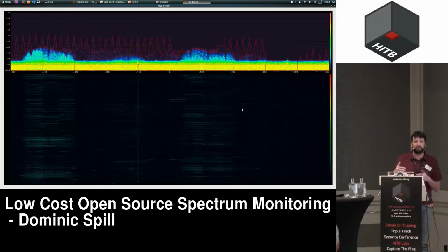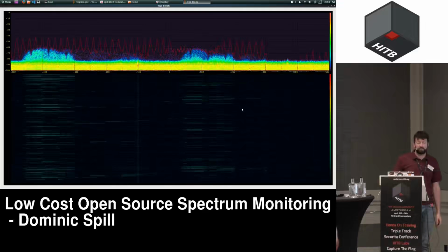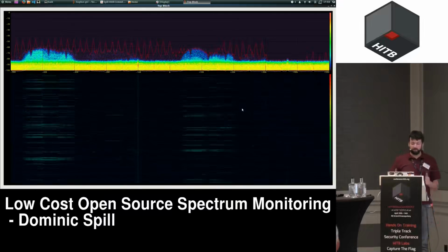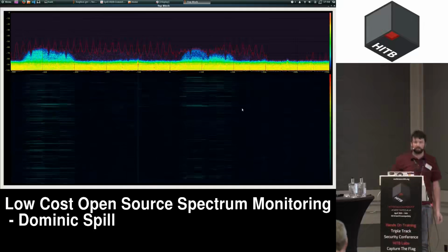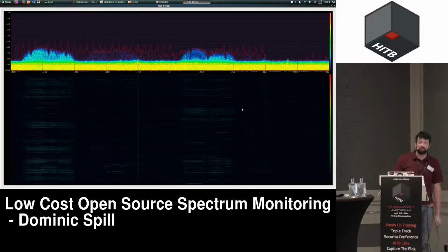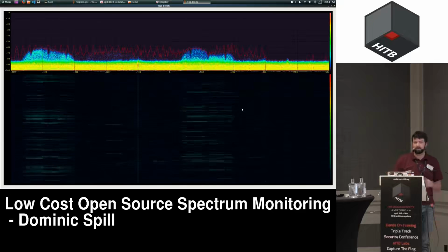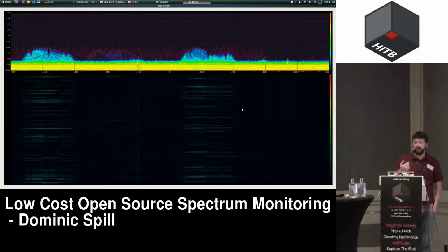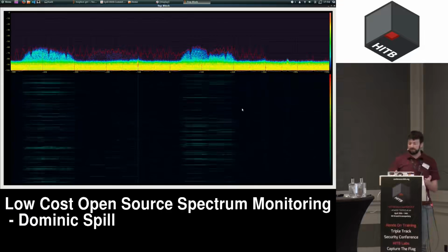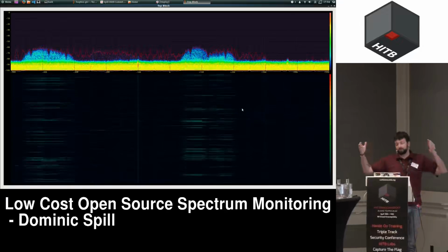But those bursts are very quick, and they're transient unless you're looking in the right place. I mean, 10 years ago when I was trying to build our first software-defined radio implementation for Bluetooth, I had to point at, at the time, an 8 megahertz wide chunk of bandwidth and just hope that Bluetooth would stroll past at some point. Whereas with this, I'm able to go and look at where it is in the spectrum. For Bluetooth, it's all over the place, so it's probably not such a big deal. But last year we were trying to reverse engineer some little wireless quadcopters that were 2.4 gigahertz transmitters, and they claimed to be 2.4 gigahertz frequency hopping, and we were able to use techniques like this to look at the whole band and work out where they were hopping to and which channels they were on, and so on and so forth, because we were able to monitor a much wider section of the band.